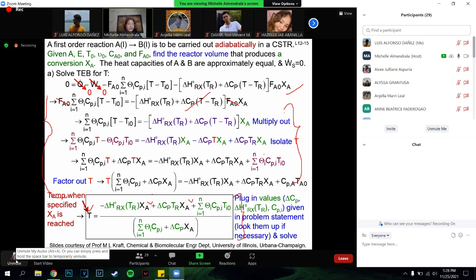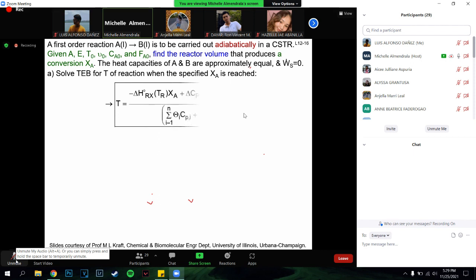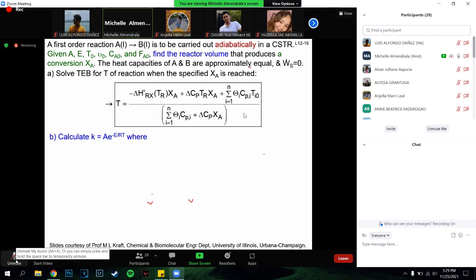In terms of CSTR, most calculations are very direct. So no need to do differential equation solution, but a simple fsolve will be enough. Okay, so that is for the adiabatic CSTR. Okay, so this is our working equation again. Any question about this equation, class? So this is the final TX relationship from energy balance for CSTR adiabatic.